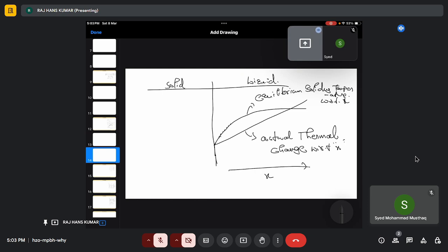And if the equilibrium temperature is higher than this, that means below this equilibrium temperature, that solid is stable. That's how you will have a dendrite formation there. That is what we call constitutional undercooling. Because of the addition of this element, there is an undercooling there. Actually, this protrusion shouldn't be stable here because of this constant increase in temperature. But because of the introduction of a solute, our equilibrium solidus temperature has changed.